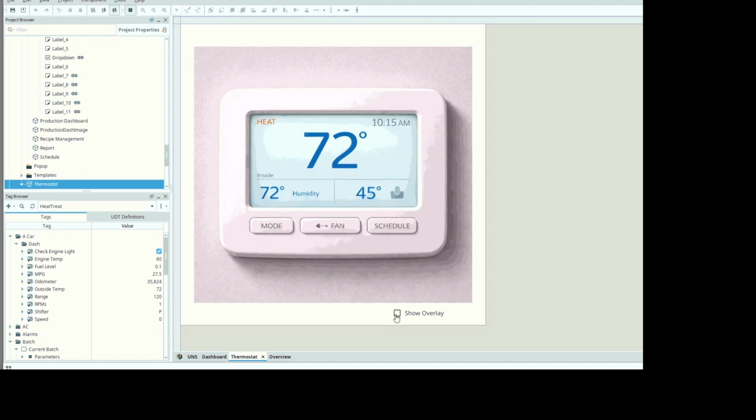Going back to our thermostat example, this is fairly similar to a heat treatment operation where we're going to be controlling the temperature in a furnace based on a set point. In this case, the thermostat would control the signal to the furnace in your attic or your air conditioning unit to heat or cool your house. We're going to be controlling burners or electric heaters in a furnace to control the heat to meet the desired design requirements for whatever parts we're heat treating.